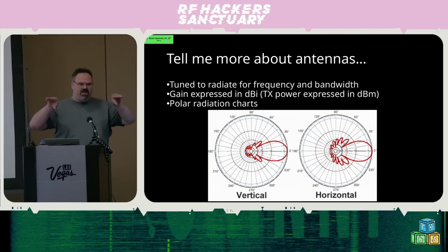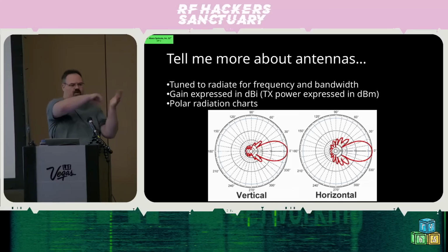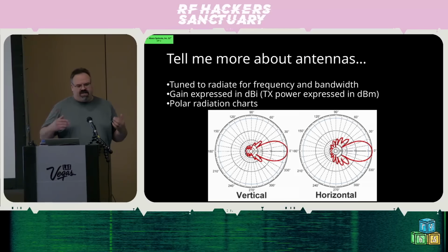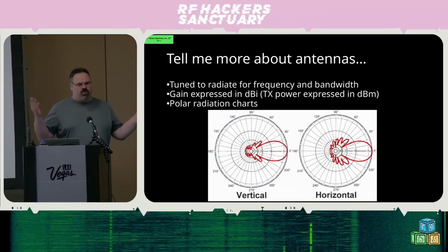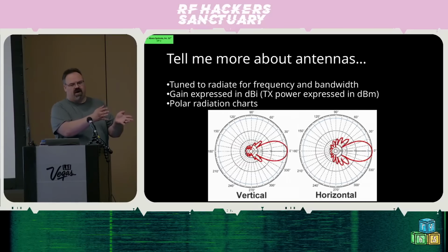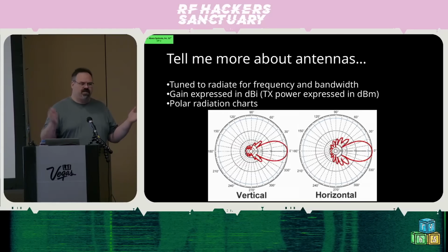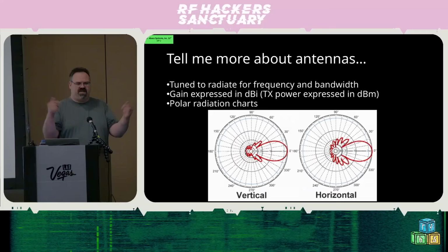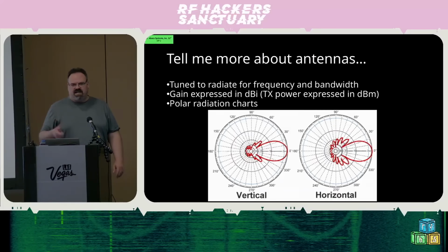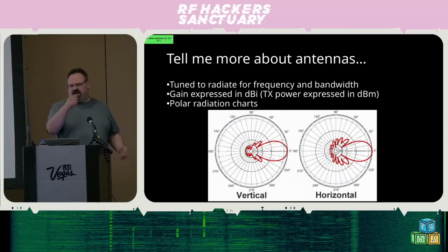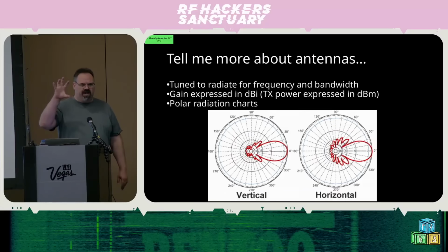So it's putting a lot more signal out in a smaller, vertical chunk around the antenna. As you increase gain, you get more signal, but in a more focused direction. You don't get something for free. Kind of like take a light bulb, light it up. It kind of lights up the room, put a reflector behind it, and it lights up a big spot, but the rest of the room is dark.